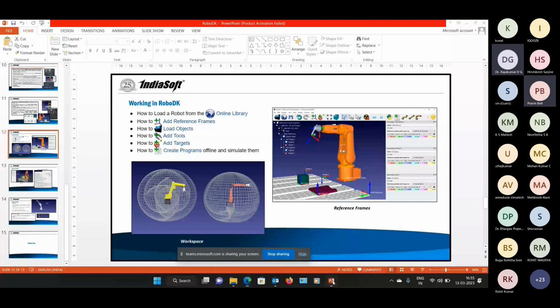You see, I think in a lot of syllabi, selection of robo is mentioned. I think you're mentioning that particular line from the syllabus. Selection of robo will depend on things like work envelope, repeatability, reach, width and speed required. All those parameters are there in RoboDK. If you go to the parameter section, they are all available there. But it cannot automatically select the right robo for your application. That we'll have to do.